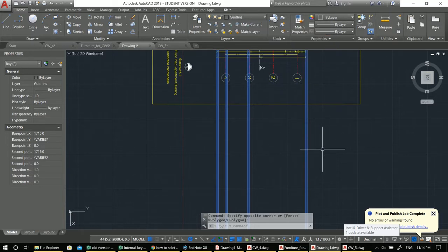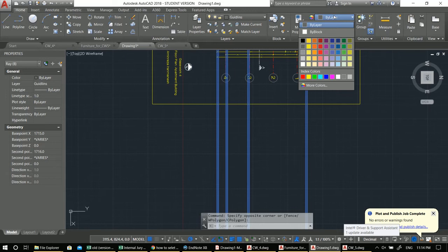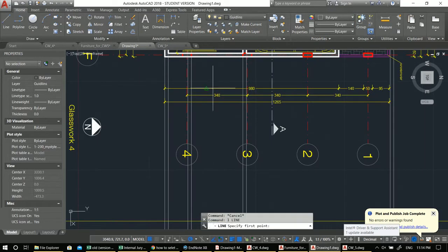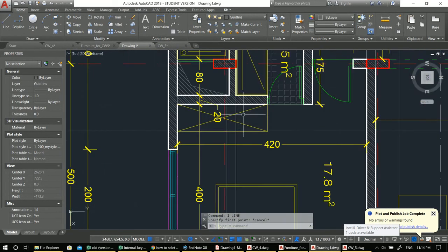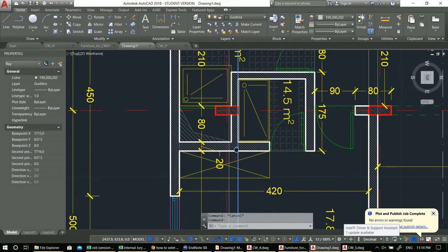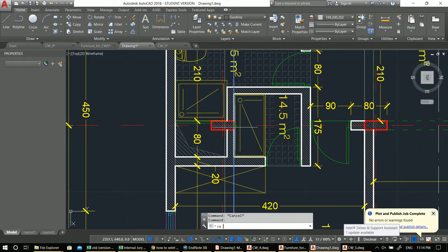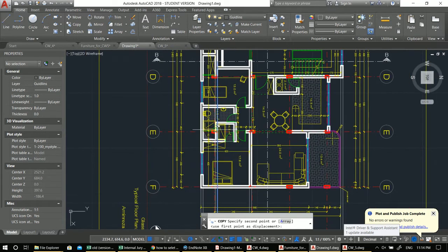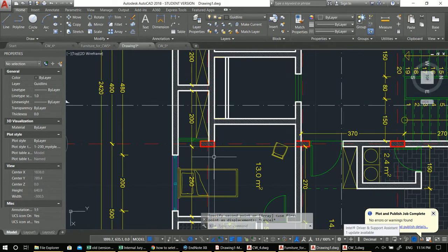So usually I change the color or line style of these to something a little bit more visible. If my drawing is usually darker gray, I will put this in one step or two steps lighter gray. Now, the next lines will be the lines that I don't cut but I see in elevation. So I have one here. Where is my line? Where is the section line?